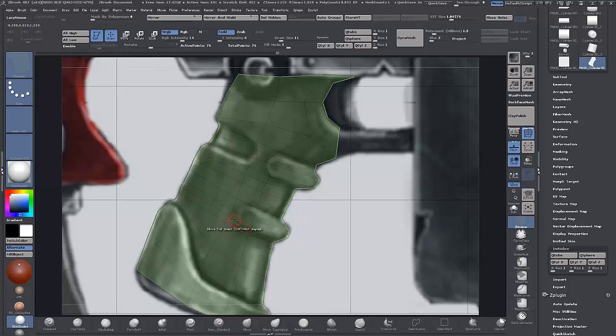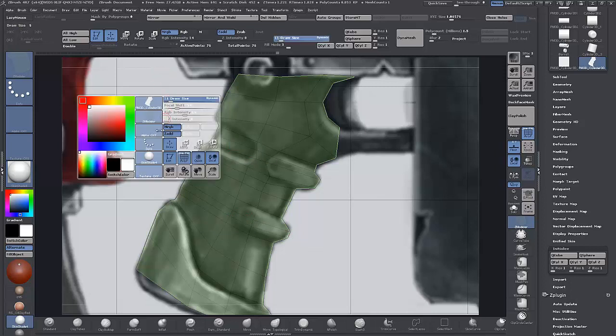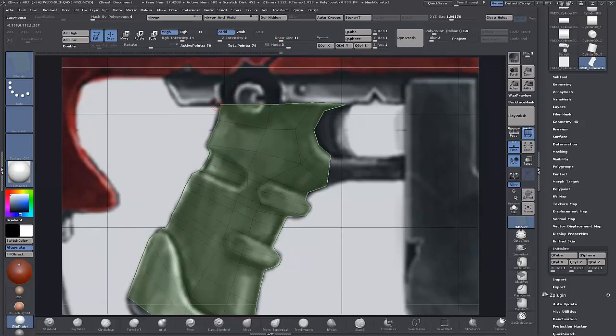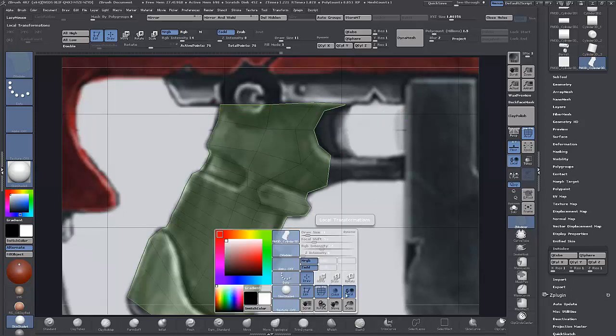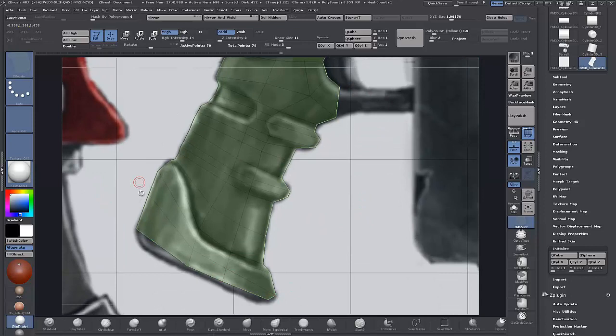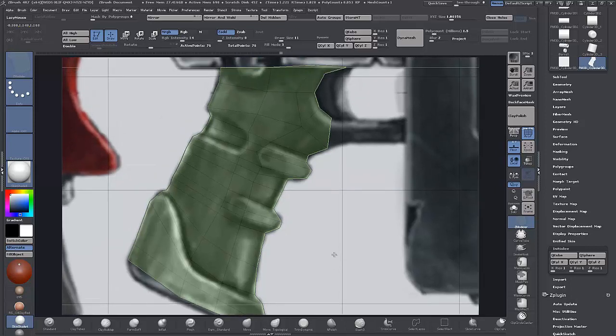So we're nearly there with the shape, so you know, it's almost time we can clip this off later on. It's almost time to Q mesh and add some more. We can Q mesh out at the bottom here, but what I'm going to do here is we're just going to inset these. Probably just make sure that you have them shaped up as you like, and then we'll just use the inset just to kind of separate them out, and then we'll extrude them.